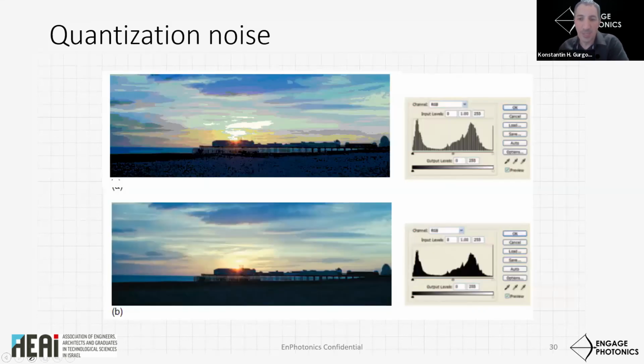So quantization noise is an important factor to take into account when considering the amount of digital levels that are utilized in practice in your application. For example, in thermal imaging applications, the image sensor can be 12-bit or 14-bit. However, often the environment's temperature is very close to object temperature, so the actual number of utilized digital levels is very small.